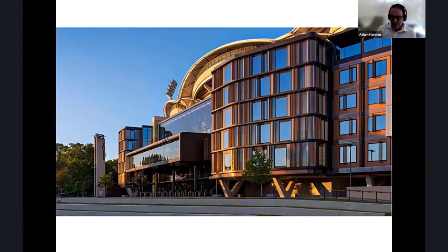During this project, and as I think it still currently is today, fire regulations did require us to put an additional fire check lining around some of the CLT in firewall conditions, even though technically the material complies with those properties themselves. So it's probably a case of some of the regulations, certainly in South Australia, needing to catch up with what the actual material properties can deliver from a CLT perspective.